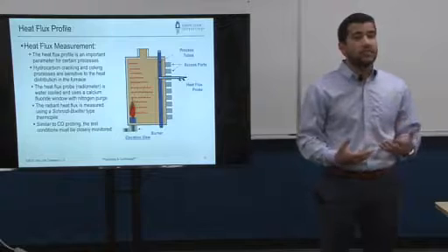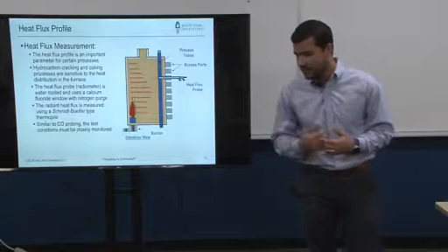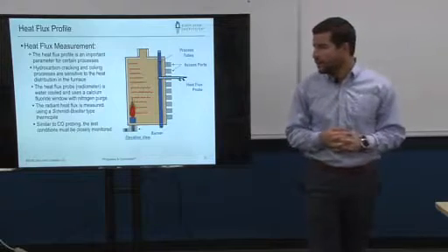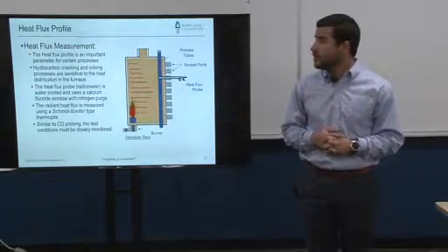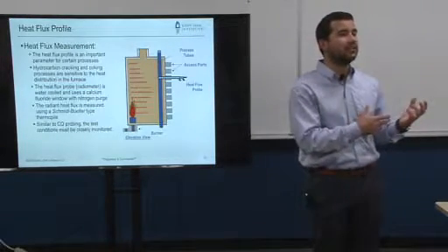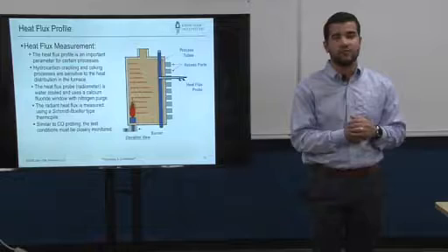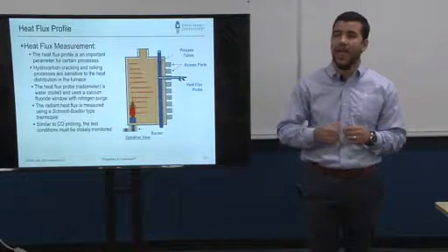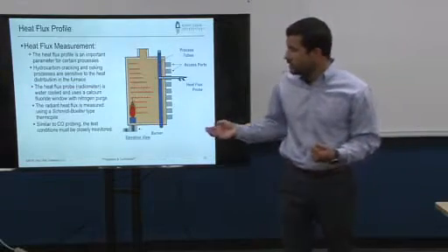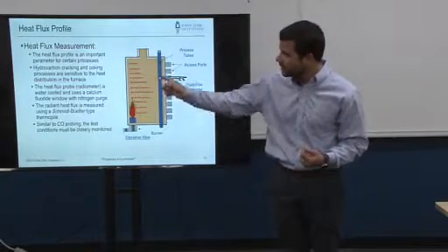There are other things that we also get to measure in the furnace, and this is for applications like millisecond furnaces, which I think crack methane. What they do here is they actually measure heat flux. They measure the radiating energy off of the wall behind the burner into the process tubes. And there are some heater designers that actually have a desired heat flux curve. So if you were to normalize the amount of heat being transferred off of the wall to the tubes, you'll get something that looks very much like that.